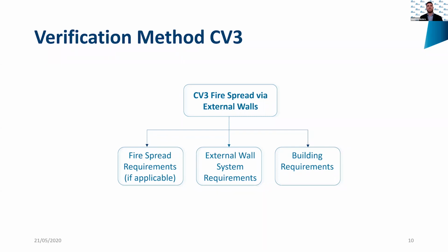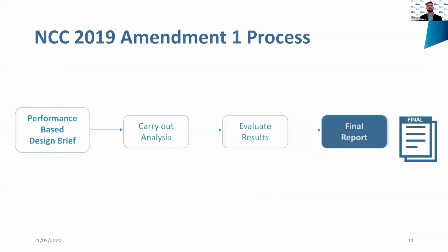So we had some questions yesterday surrounding the use of FV1, which is a verification method that can be used to comply with FP 1.4 for external wall weatherproofing. And there are some potential situations where people ignore the risk score that needs to first be established. So it's important that if you're using a verification method as the means of compliance, you're going through everything. And if you're not, then you're documenting it as a specific performance solution. So just wanted to highlight that.